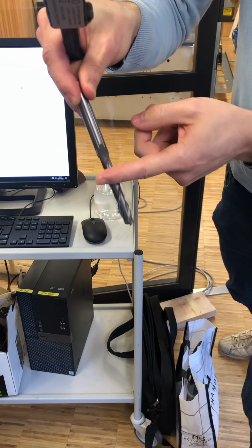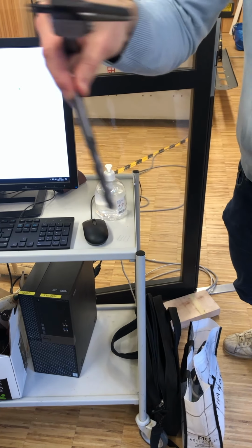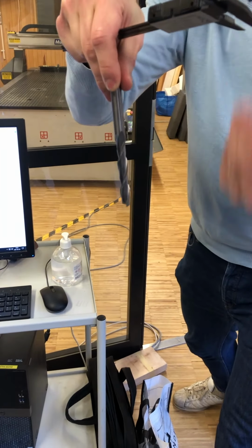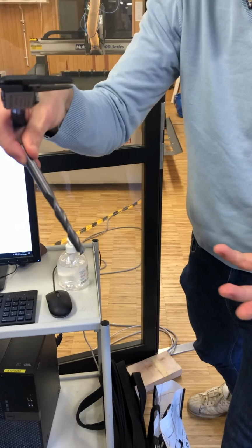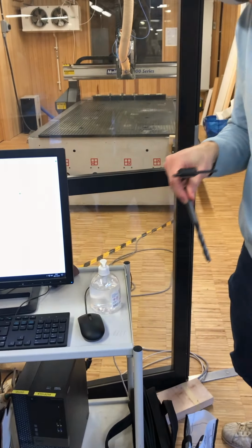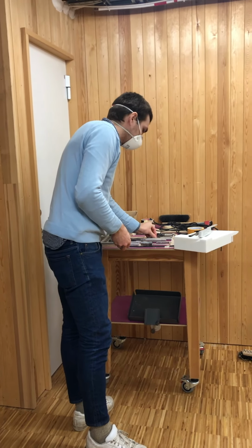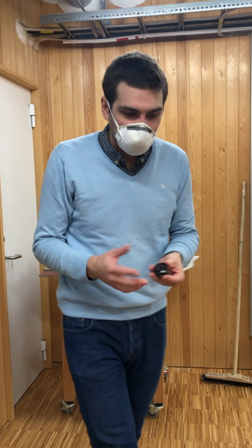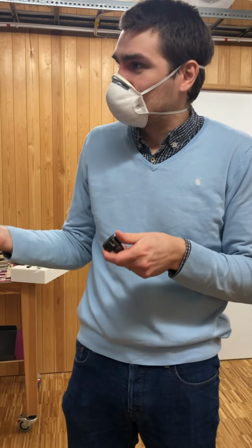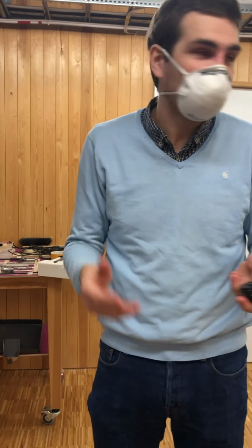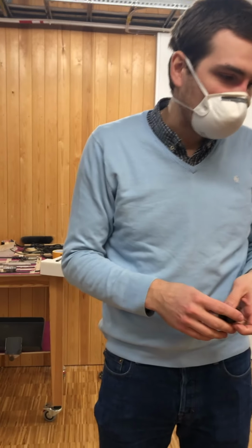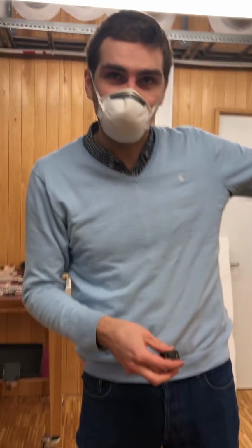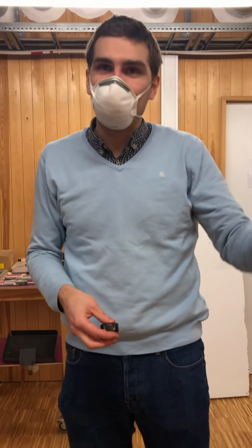So if you move further down than this in a material, especially if it's a small pocket or something where it cannot extract, then you will have a problem. That is something to take into account. So now the warm-up is complete, and we took the time to make sure that the tool number was set to 1, so we should set it to 1 as well. That is something to take into mind because right now tool number 1 is the warm-up tool.